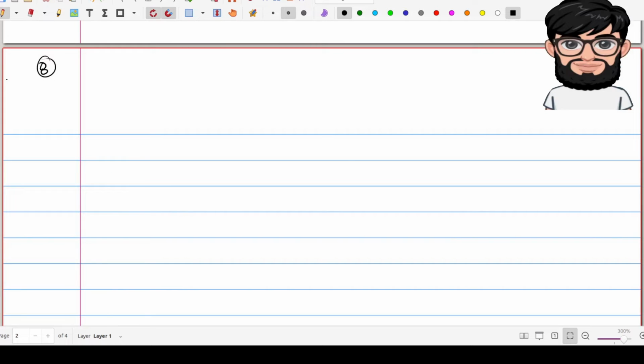Okay, what is the standard direction of turns when approaching an uncontrolled airport for landing? Just remember, if it is an uncontrolled airport, they do not have any ATC. All turns must be made to the left, unless a traffic pattern indicator indicates that the turns should be made to the right. So if nothing is mentioned with the airport description on the sectional chart, always remember that all turns should be left.